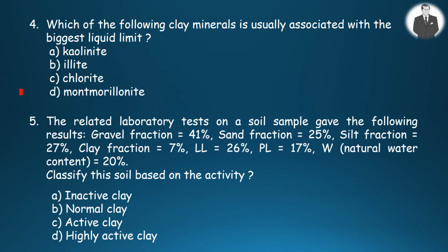Now the fifth question. The related laboratory tests on a soil sample gave the following results: gravel fraction 41%, sand fraction 25%, silt fraction 27%, and clay fraction 7%. Liquid limit is 26%, plastic limit is 17%, and natural water content of the soil subjected to those tests is 20%. Classify the soil based on the activity.